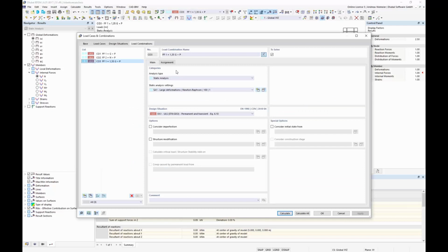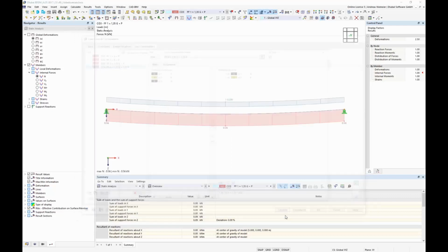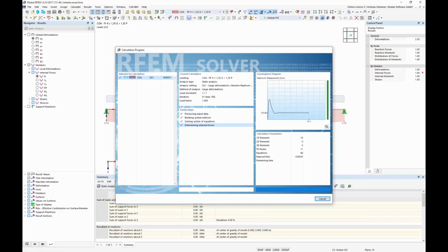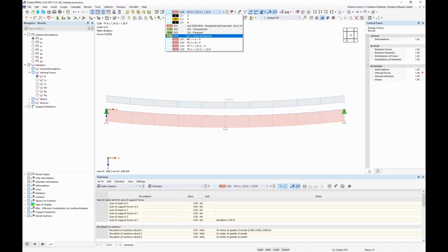Of course we can also, let's say, scale the pre-stress. What means if I scale the pre-stress 1.35 and only for the name here 1.35 form 4, for example. This was form 3, only that we have a clear description, and calculate, then we can also scale the form finding inputs. You see not 200 and 270. What is the factor 1.35 in between with the corresponding force again. So it's an easy game to work with different shapes in one program now.